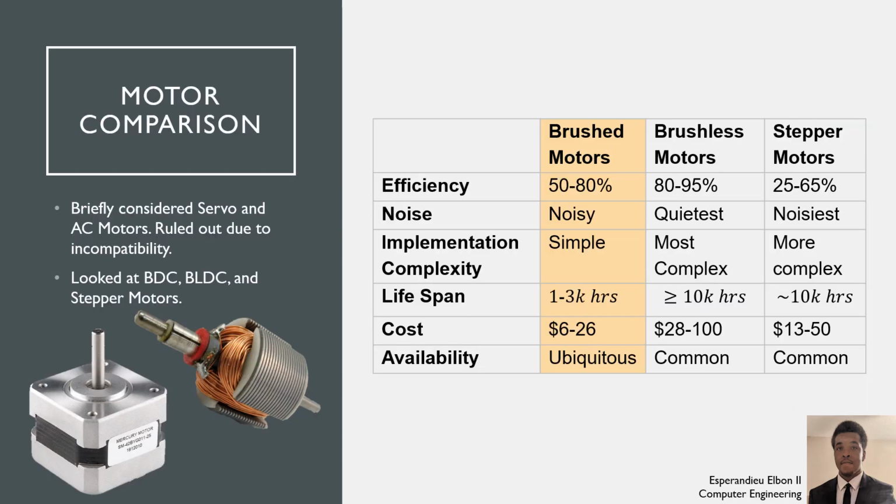Mobility is probably the largest differentiating factor between S.E.E.M.S and similarly placed systems. This necessarily calls for choosing motors. The deciding factors between the three types considered here were cost, availability, and complexity. Though brushed motors are noisier, less efficient, and less precise than stepper motors and brushless motors, they are infinitely more available, a lot cheaper on average, and much simpler to use.